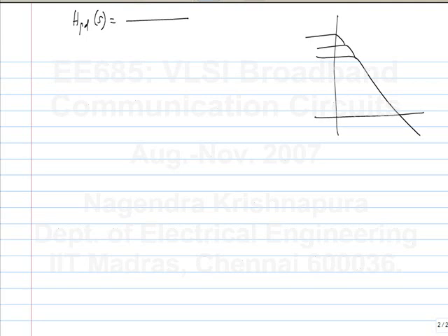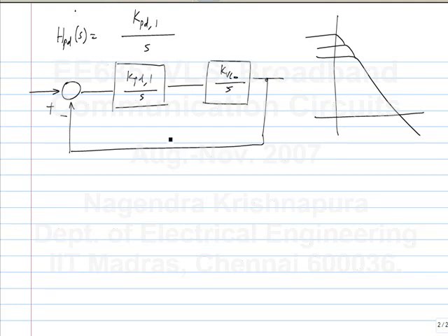So I'll say the phase detector transfer function is some K_PD,I by s. That subscript I indicates that it's an integrating transfer function. Okay. So if we have this, we also have, of course, 1 over N. So this is the loop we have, if we replace a phase detector with a constant gain with a phase detector which behaves like an integrator.